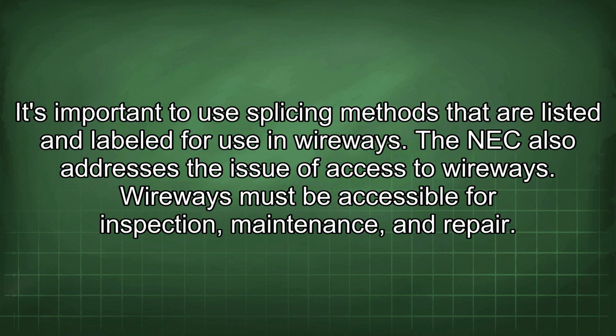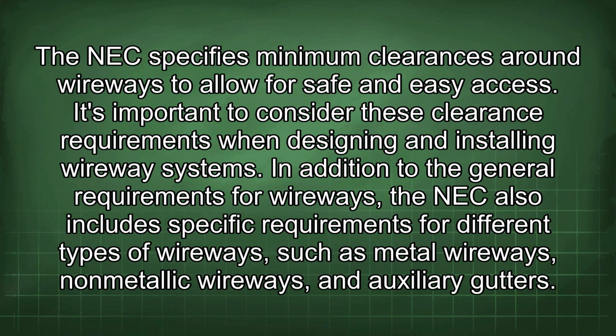The NEC also addresses the issue of access to wireways. Wireways must be accessible for inspection, maintenance, and repair. The NEC specifies minimum clearances around wireways to allow for safe and easy access. It's important to consider these clearance requirements when designing and installing wireway systems.